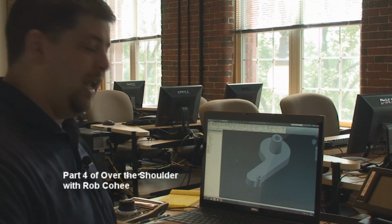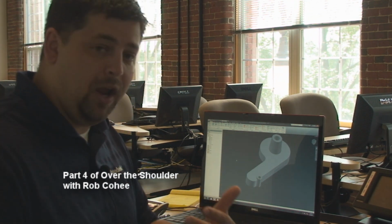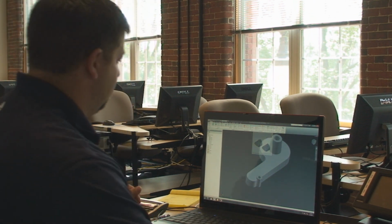Now, rather than doing that 8 different times, evenly spaced 72.6 millimeters all the way around, I'm going to utilize the rectangular pattern command. I giggle because it's not necessarily rectangular. I'm not going in one direction and then another. I'm actually following a particular path.